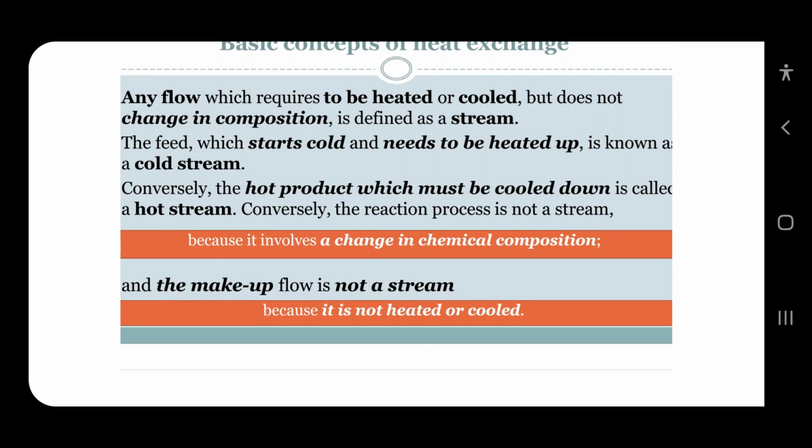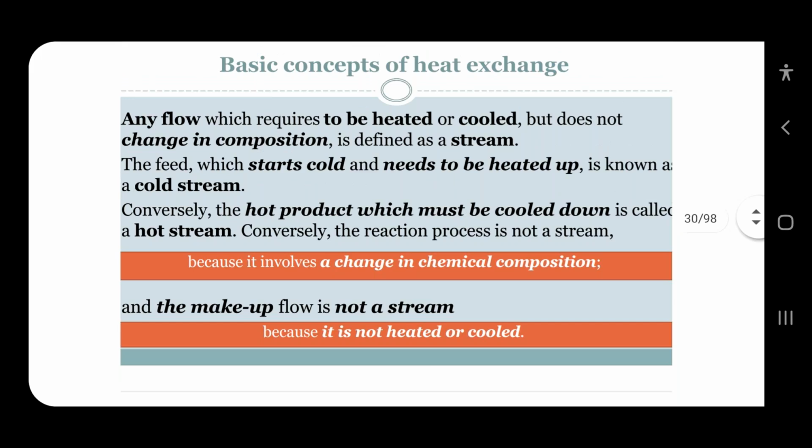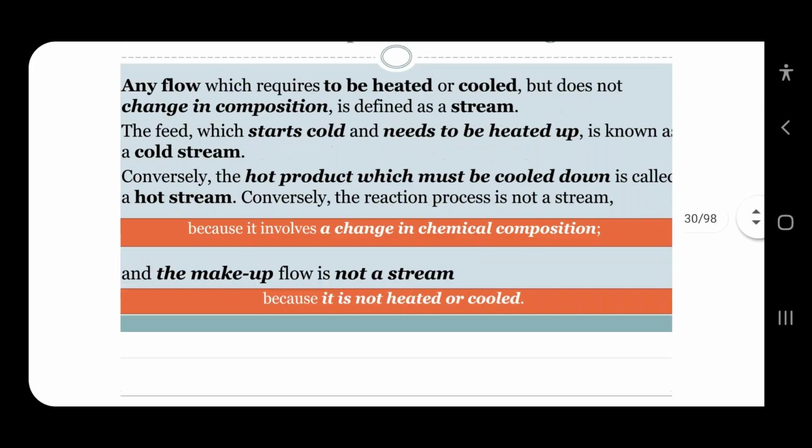The makeup flow is not a stream. If you add something or make up the stoichiometry of the reactions, that is not part of the stream. A stream only indicates that it is to be heated or cooled but does not change in composition. One that starts cold and needs to be heated is a cold stream.